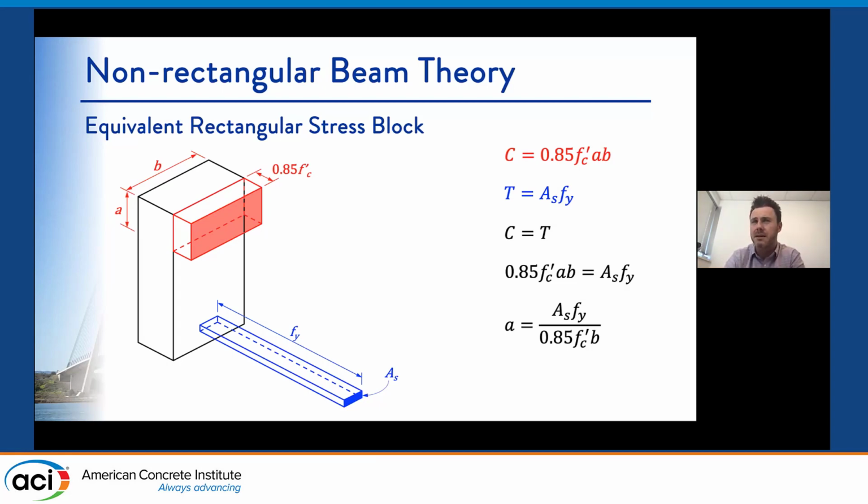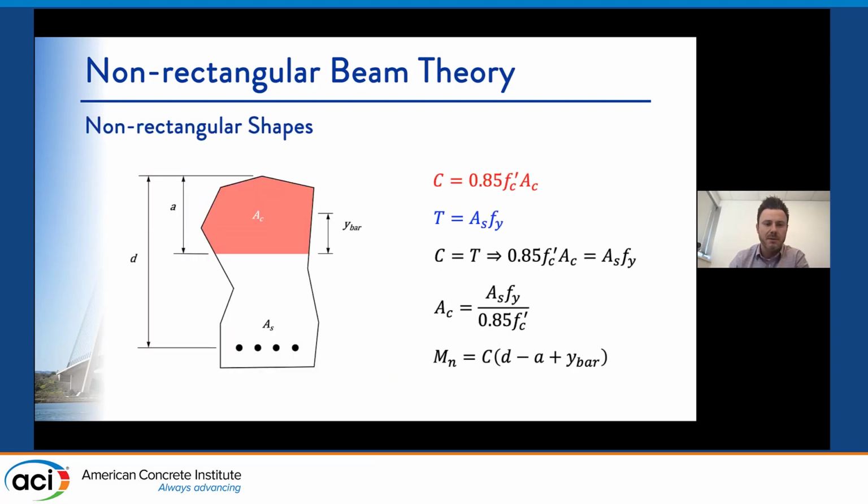And I think that's another point to drive home when you're getting into flexural analysis and talking about it. For a rectangular beam, it's pretty simple, right? So we can do that. Then we go check to make sure the steel yields, that our assumption was true, and we can continue to calculate our nominal moment capacity. But when things get a little bit funky, and this is overdoing it a little bit here, when you have a non-rectangular beam, you can't do that anymore.